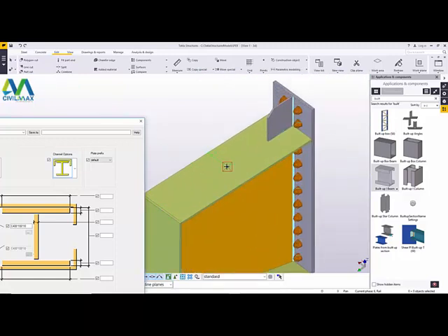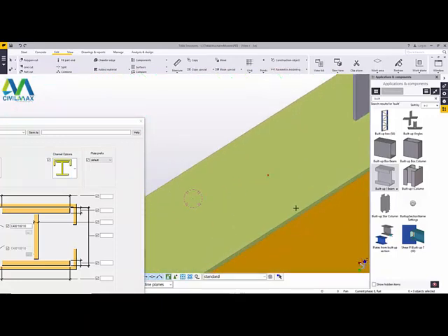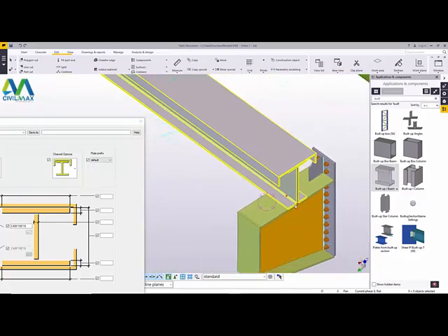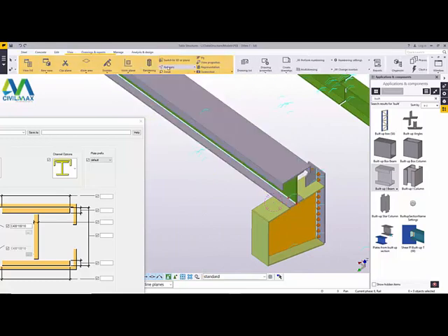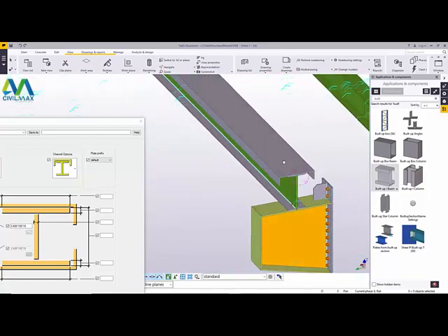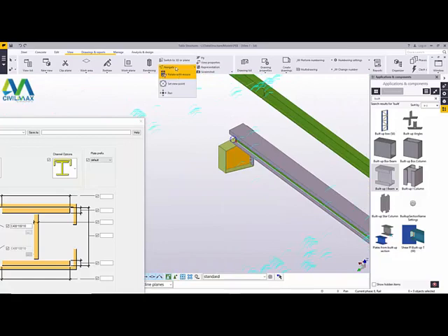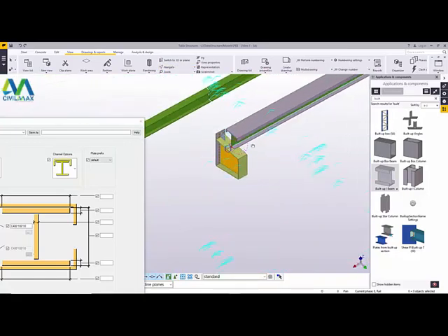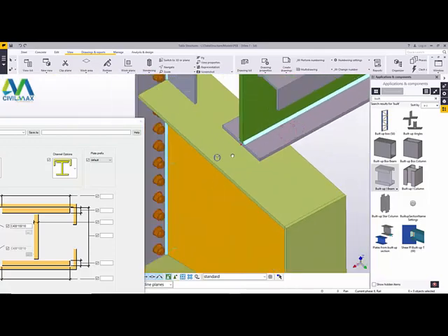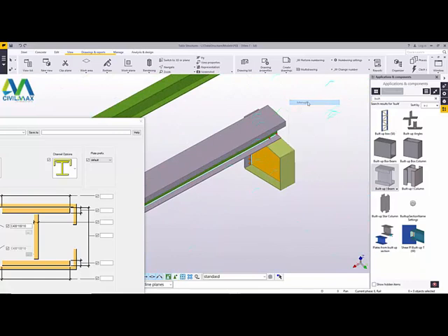Now I'll snap at the midpoint here, the point we've just created, and stretch away from it and snap right at the edge of this. Perfect. Now here we are, and before making an inch further, make sure everything is in the right position, because if you make a mistake, you'll find everything following a different direction that you didn't intend to go. Now let me come on this side also and check whether my beam or my girder is sitting in the right position. Well and good, it is there.